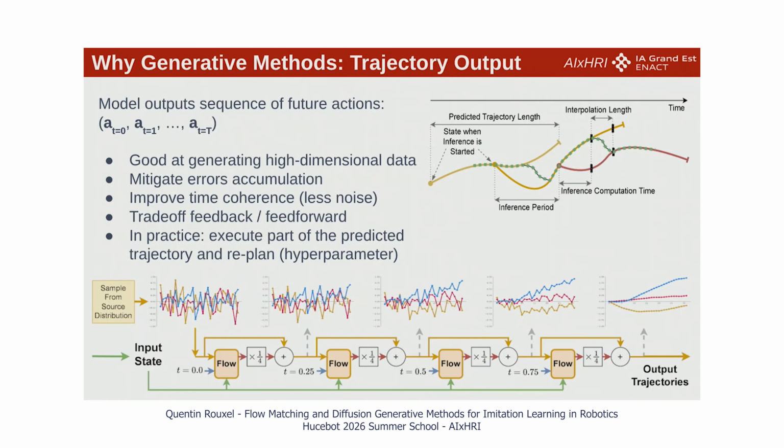On the other hand, we could have, let's say, feedforward. Feedforward means we plan what we want to do, and then we close our eyes. We don't care anymore about the external world, and we keep believing in ourselves, let's say, and we keep applying the actions we have planned. Of course, we need to find a balance between the two, between reactive and feedforward, but very often, when we do classic robotics, a bit of feedforward helps a lot in stabilizing control. First, because feedforward is less sensitive to noise in the sensors. If you have a purely reactive policy and you have noise in the sensors, you will have noise in the output, which is transmitted directly.